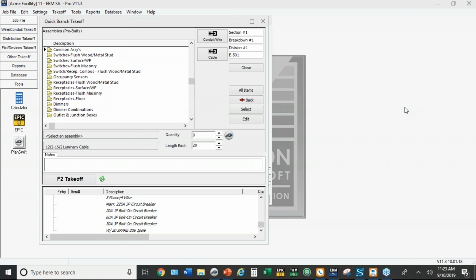Couple things I noticed. Now you said you take off one junction box for your home run. I'm assuming, was that 3 circuits or 6 circuits? 3 circuits, and there were 10 home runs, so I did 10 J boxes. Okay. So normally if I do a home run, I'll do three junction boxes, but that's just the methodology, because I'll do 3 circuits and say we drop one in this room, one in that room. Yeah, no big deal. I said, you can't have too many J boxes.